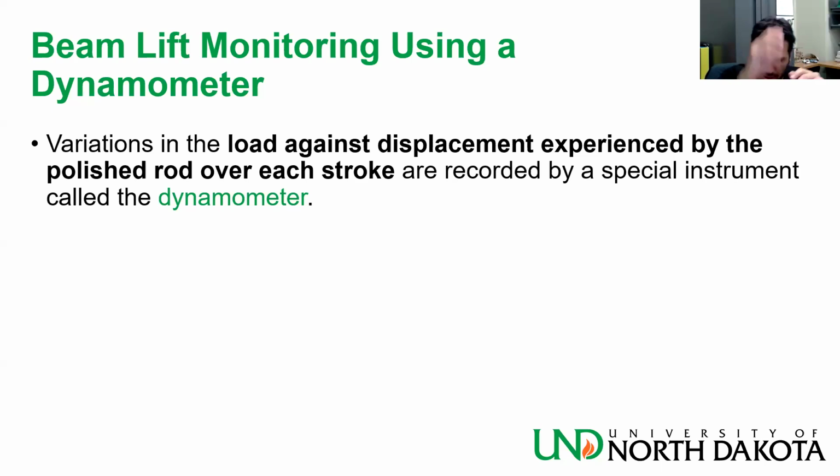Now, there is a very long string of sucker rods, and actually, if you see some, try to see, you'll see that you can twist it even with your hands. They are very, very easy to break. Extremely easy to buckle. I bet if you step on them and try to push it, you can actually destroy one.